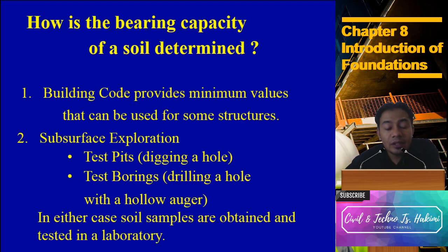Okay, how is the bearing capacity of the soil determined? How can we determine the bearing capacity of the soil at the site? First, we can refer to the building code, which can provide a minimum value that can be used for some structures. And then second, we go to the site, and then we can perform the subsurface explorations.